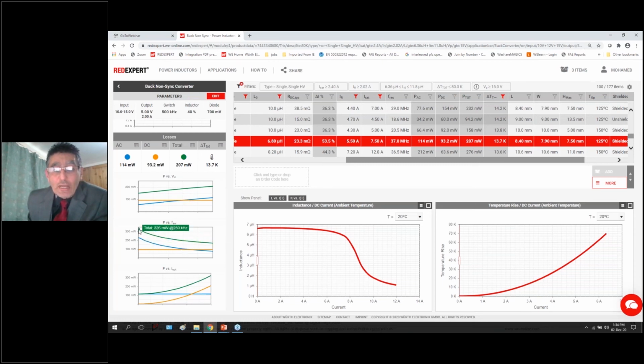We'll also show you what happens if you decide to change switching frequency. So we've said 500 kilohertz. If you go down, you're going to increase losses quite substantially in that particular inductor. If you go up, you could drop it down. Now, playing with frequency, I said, is your degree of freedom before. But naturally, we also have to take into consideration losses in the transistor switch as well, and the diode. So that's also part and parcel of the overall. And we show you as well the impact of load on the overall losses as well. So if you change your load beyond 2 amps or below 2 amps, how that impacts things as well.